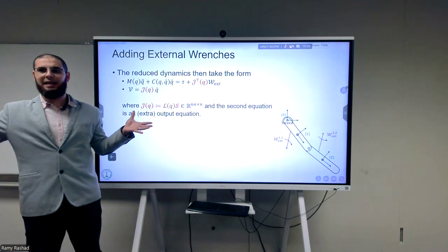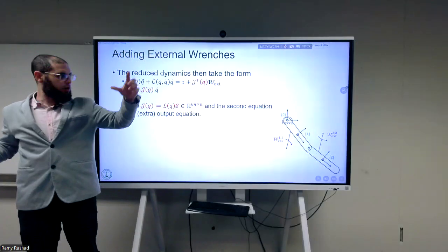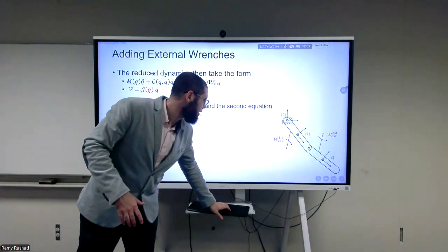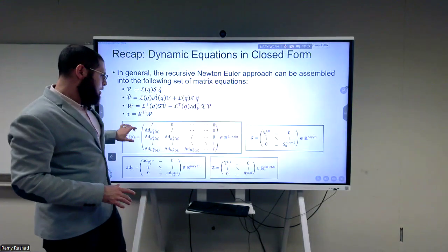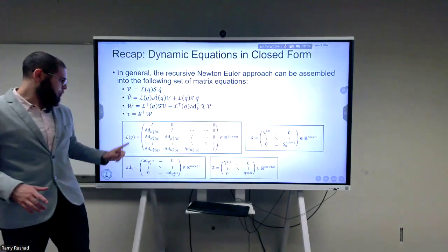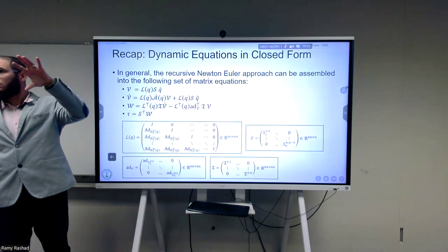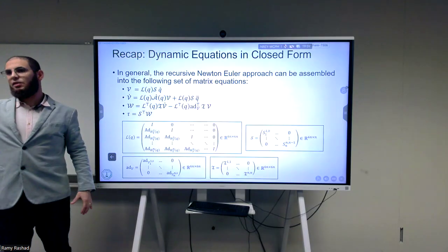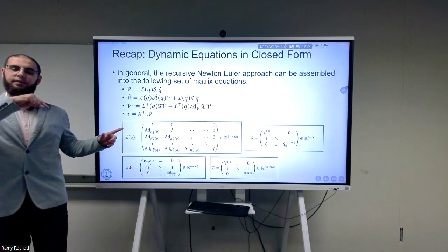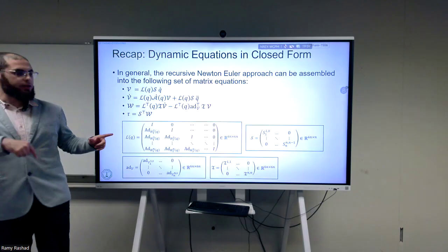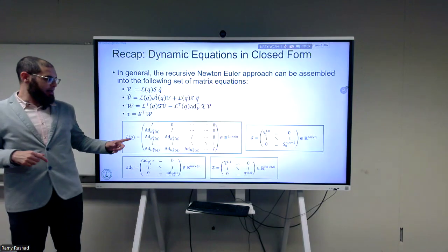It was this huge matrix. It was just the L multiplied by the S. The S itself was block diagonal, and the L was a very huge matrix. Let me remind you with it. So this was the S, and this was the L. If you look at the S, it was just a block diagonal of all of the screw axes that we have for every joint, expressed in the link's frame. Usually it's expressed in the child frame in this S.